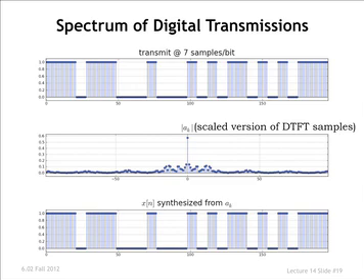So when you see these plots, you'll see a magnitude A of k, a symbol associated with the discrete time Fourier series. These are actually Fourier coefficients associated with the periodic replication of this signal outside. So it's a discrete time version of the Fourier series you may have seen in 18.03. All you have to do when you see a plot like this is think of it as a scaled version of the DTFT samples.